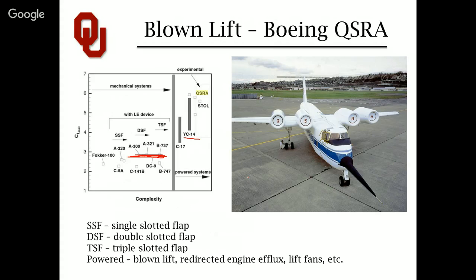The pressure in that flow is generally lower than free stream. So by shoving a lot of high speed air over the top of these airfoils, they generate a lower pressure region. And you could think in a certain way that it quite literally sucks the airplane up into the air due to powered effects. Again, the downside of this is if your engine fails on takeoff, well, at best you're going to be surprised back down here and probably be in for a very hard and flammable landing.